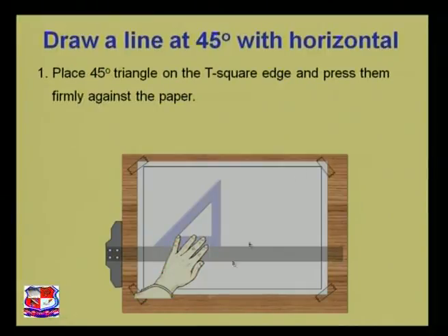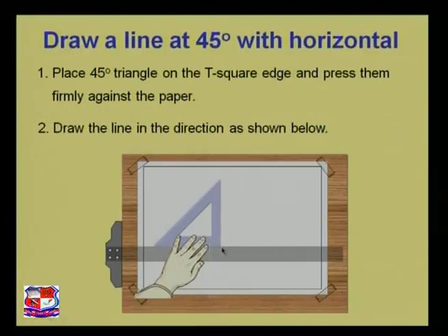Hold the T-square and the set square firmly so that it cannot get inclined. Draw the line in the direction as shown below. Don't forget to rotate the pencil.